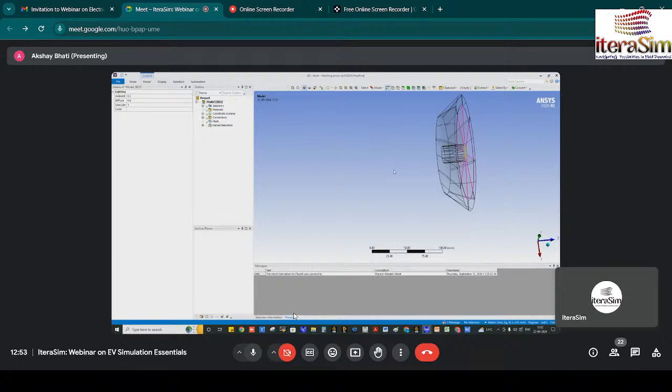There are two ways: one is how many layers you want and what the thickness should be, because near the solid body the layer would be finer, with minimal gap. But as we go beyond that, away from the solid or rotating part, it would be coarser because of the growth rate.